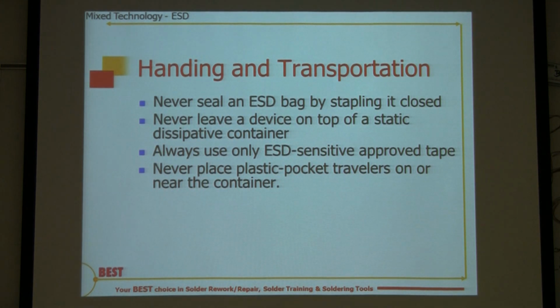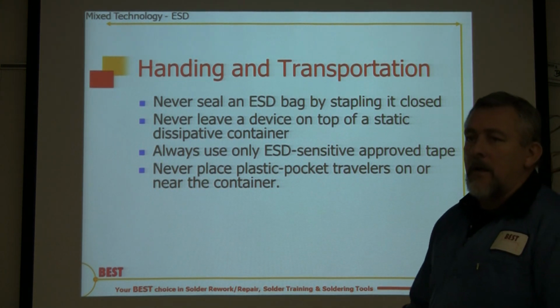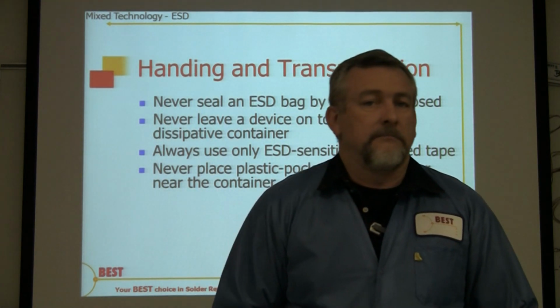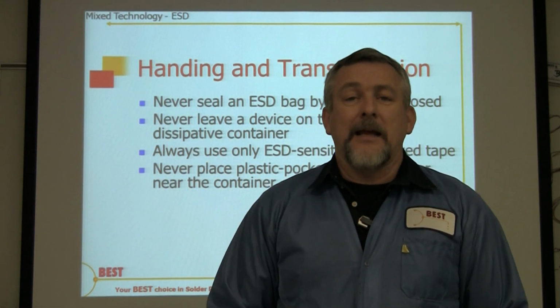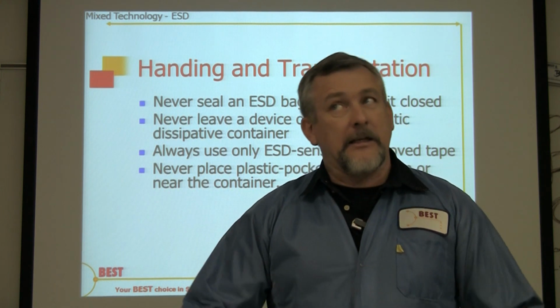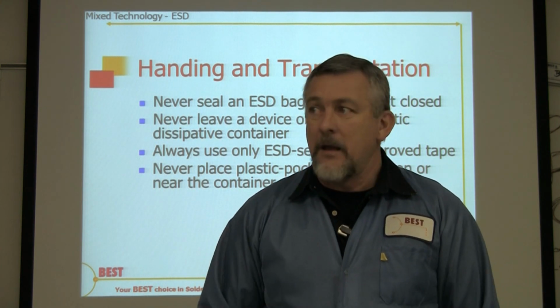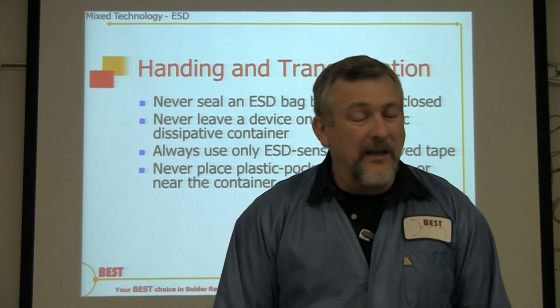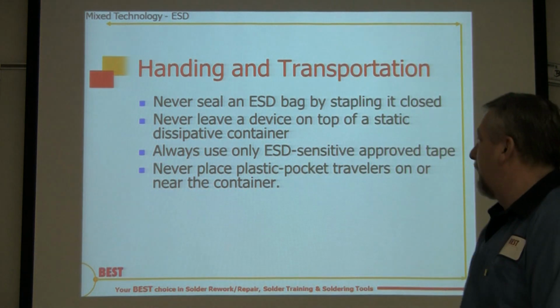Never seal an ESD bag by stapling it closed. You're poking holes in it. Now is it protecting anything? That's like trying to fill a bucket up with water and it's got a lot of holes in it. Is it going to keep? It's going to take you a lot longer, and it might not ever fill up. So think of it that way.